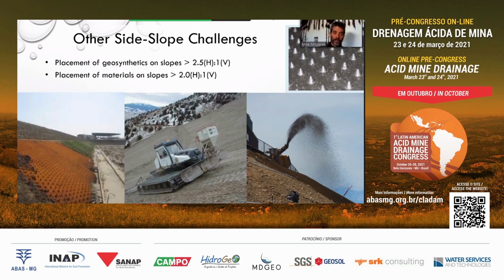These are geocells, which are quite an interesting technology solution where you can put topsoil into the geocells and it will stabilize the topsoil from eroding. And so this is in general, again, for more humid environments, but you need specialized equipment as well once you start getting above about 2.5 to 1.